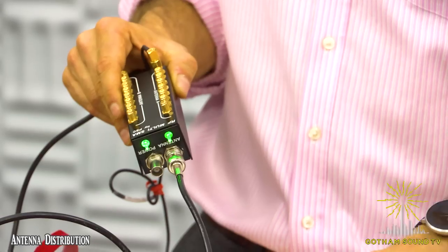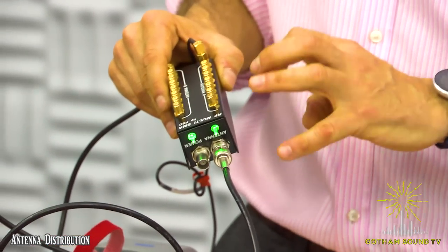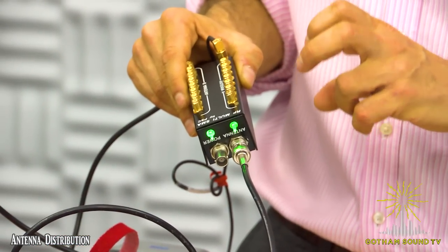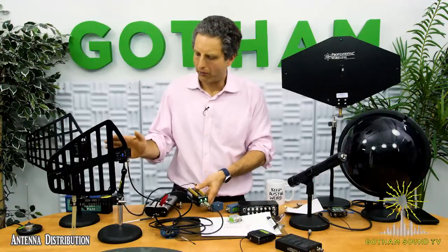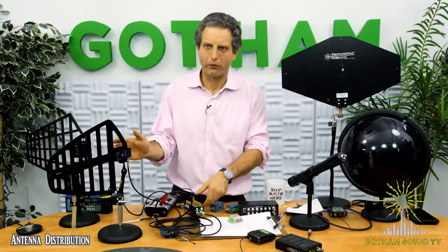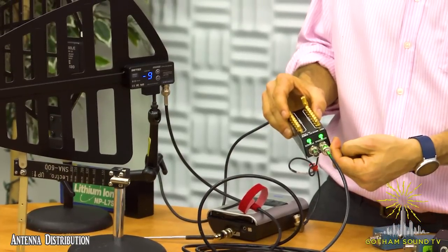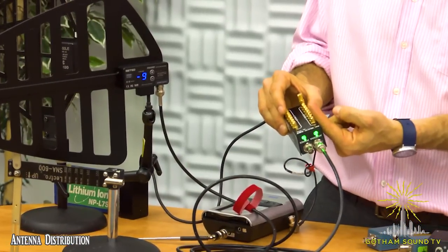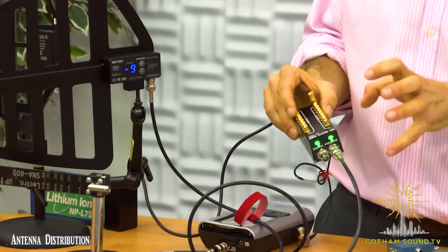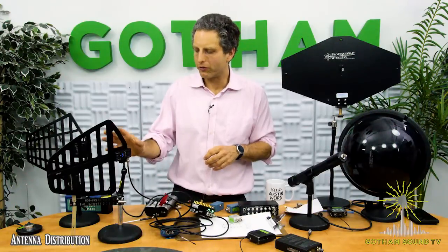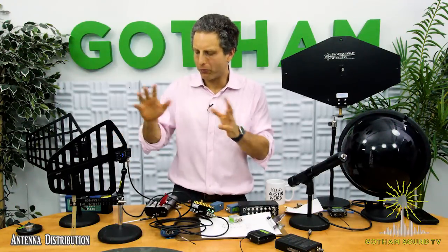But there's also an amplifier in here that overcomes the inherent loss in the 8-way splitter. So just to wrap that thought up, signal coming in here is going to come out at the same level because the amp is set to unity gain. So your job in coming up with a design is, when you choose an antenna, you set the gain based on your anticipated losses through the cable.